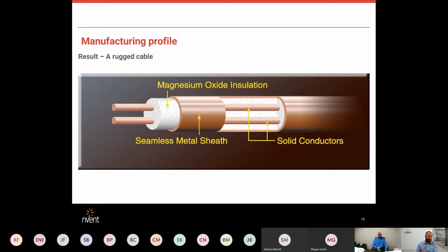We have technologies that can maintain up to 250 degrees Fahrenheit and higher with our self-regulating cables. However, the materials that we use, the polyolefins and the fluoropolymers, have their temperature constraints. So when you get into applications above and beyond those temperatures that the polymeric cables can withstand, that's when you jump to an MI cable.